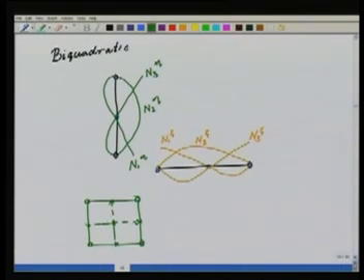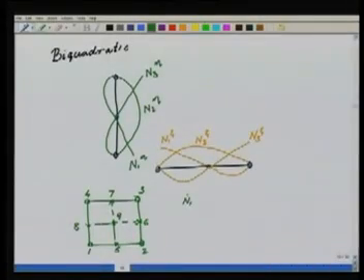Like this. I'll call this point 1, this is 2, this is 3, this is 4, this is 5, 6, 7, 8, 9. Okay. So again, depending on the point which lines it lies on, I will find the corresponding shape function. Like for example, n1 hat as a function of psi eta should be equal to, it lies on the first point, it has the first node of the psi side, first node of the eta side, so it should be n1 psi into n1 eta.